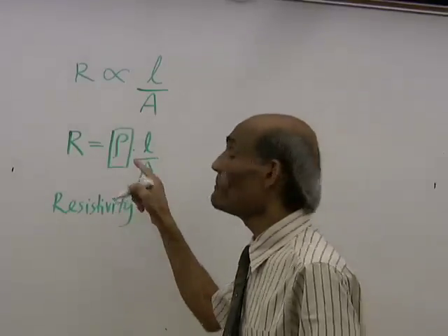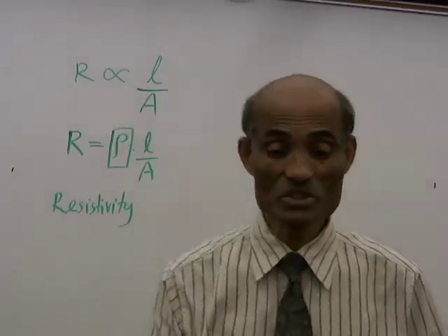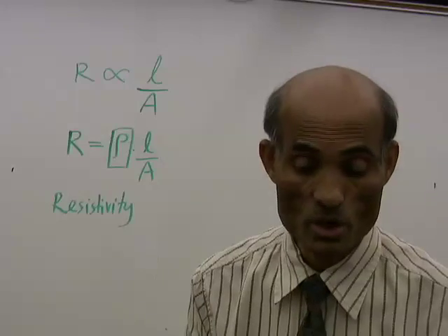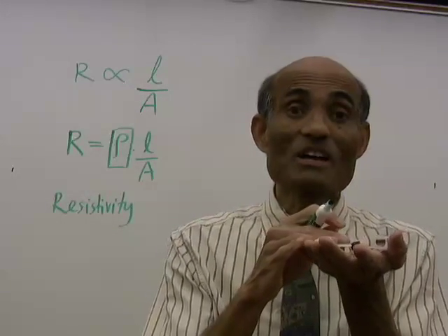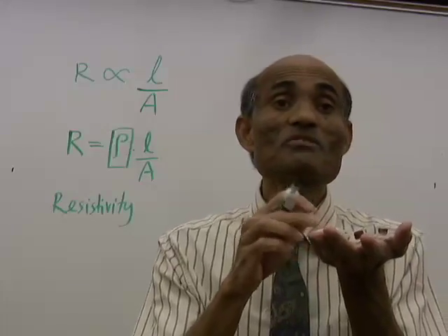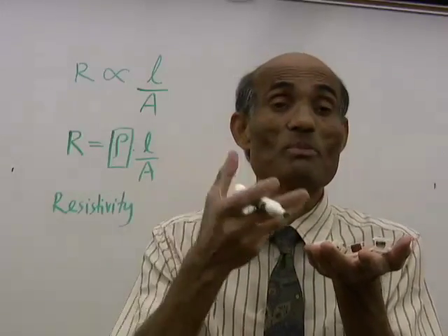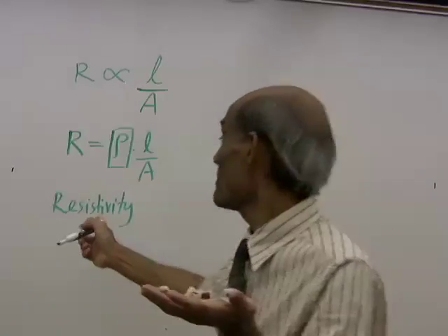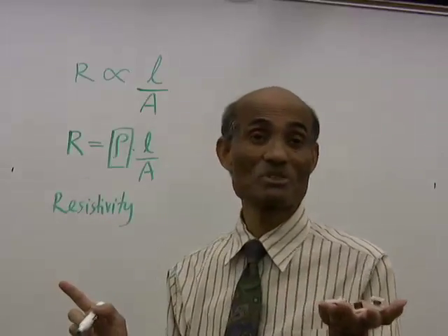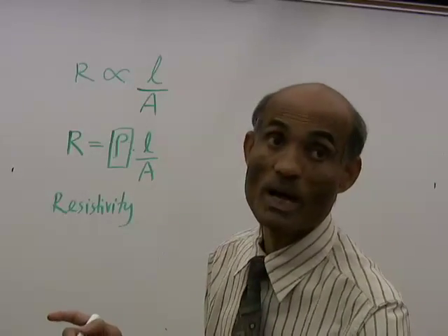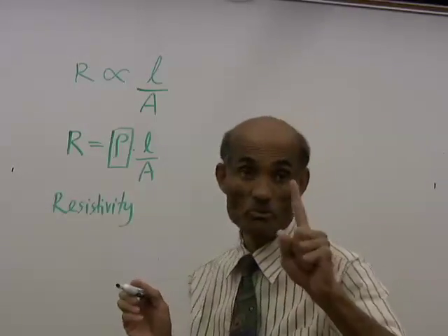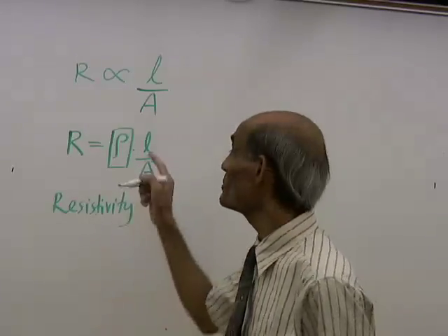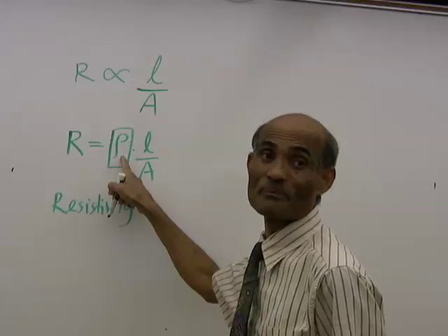And we will be measuring the resistivity of the material of these 5 conductors. Actually, the material of these conductors is nichrome. And we will be measuring the resistivity of that material. Alright, in order to do that, let's rewrite this equation. But before that, what is the unit of resistivity?